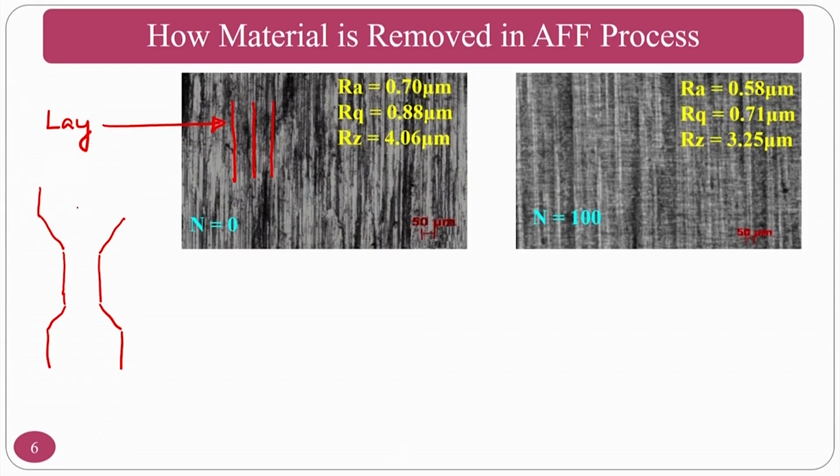So, what will happen here is, whenever you reciprocate the medium, the medium flow direction will be like this. So, always you place the grinding marks perpendicular to it. That means that on your workpiece, if I adjust for understanding purposes, the grinding mark should be like this.